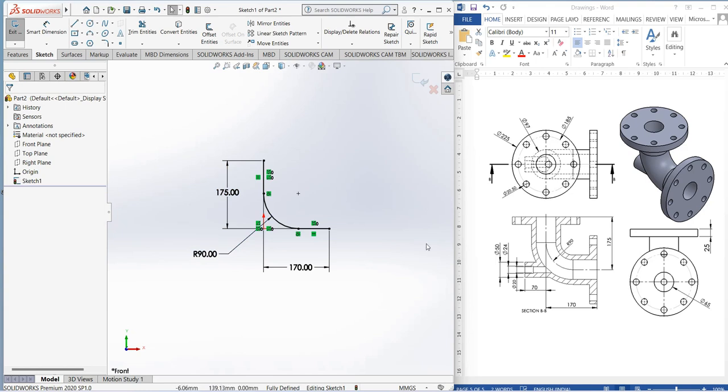Now what we need is a sweep profile of a circular profile, but you can see here our structure. You can see here this dotted circle, this one which is a hidden circle on the top view. You can see this is the edge of this circle, this one, the side edges. So this is dia 75, and throughout the whole diameter is, you can see from here, 65, because we can see on the side view this circle, right?